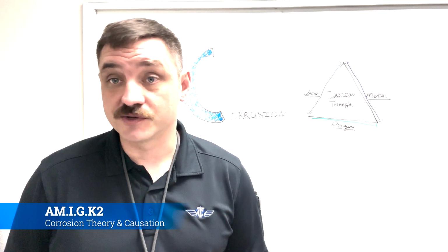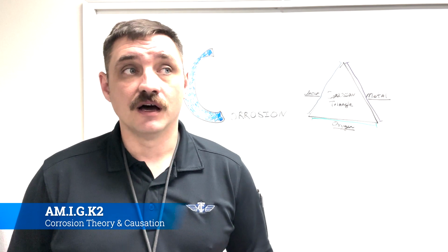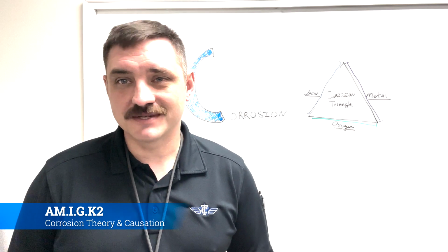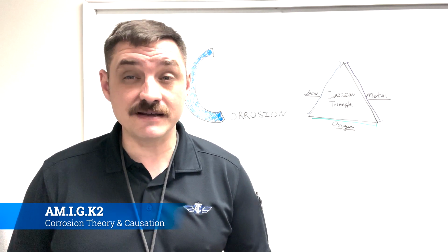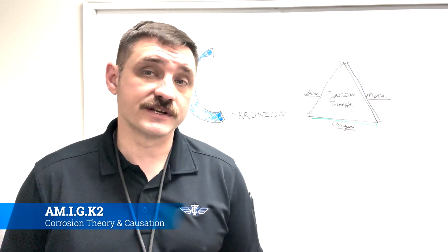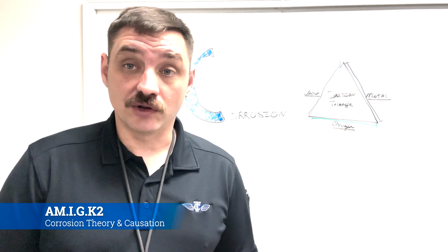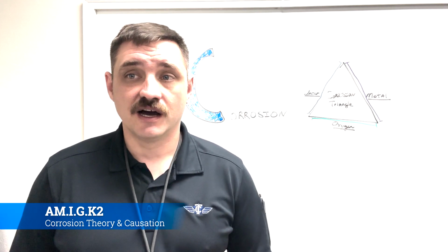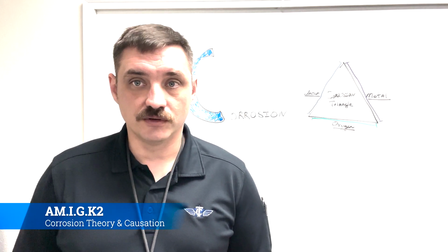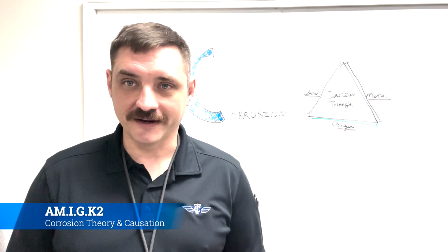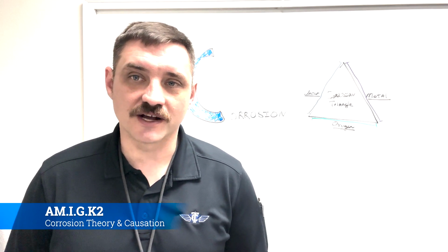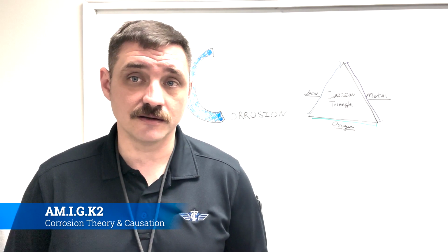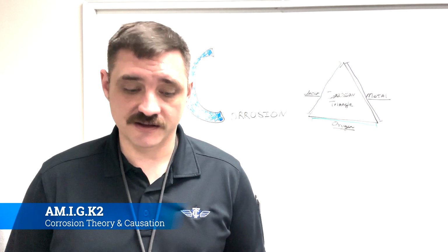Those are the type of metal. So some metals corrode differently. All metals corrode differently, but some of them corrode way worse than other ones. If you think of titanium, it corrodes, but extremely slowly. That's one of the reasons why titanium is a preferred metal, because it's naturally corrosion resistant. Whereas if you look at iron, it will corrode before you even put it on the airplane. You'll start to see that orange oxidation show up. Aluminum is more like titanium. It's slower, but it does do it. It'll pit and it can be pretty bad. But type of metal is a factor.